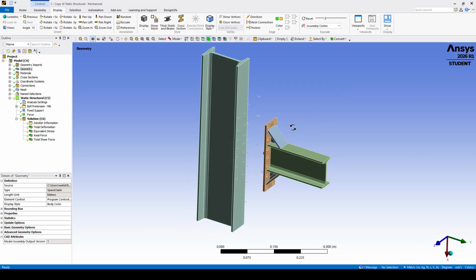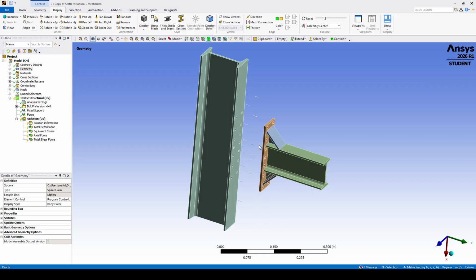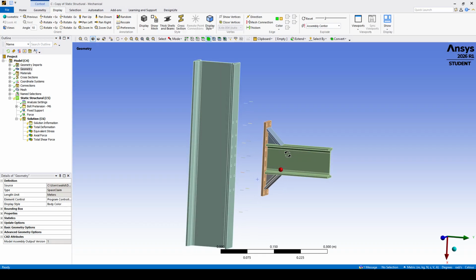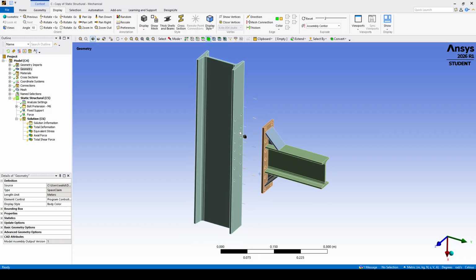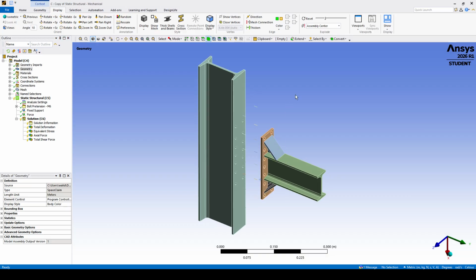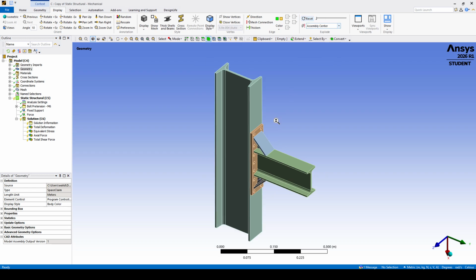What we are seeing right now is that overall this group explodes together, which means they are glued together. We have the beams, which are also separate, and this profile. So this is just a small check to see if our shared topology is defined correctly.